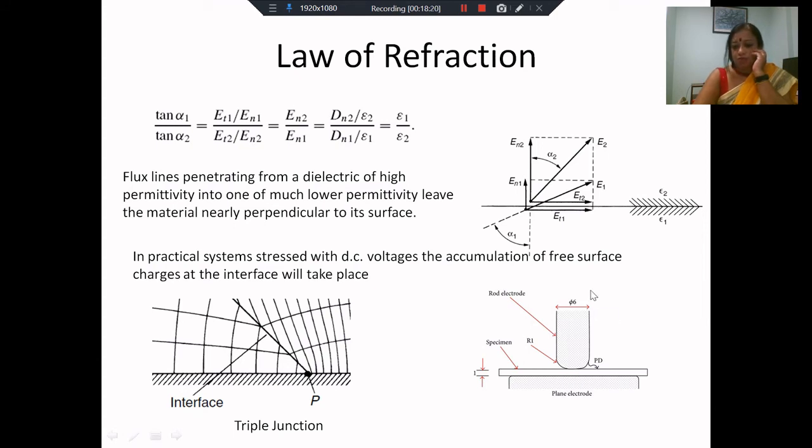This is a rod plane electrode, and there is a chamfering at the edges. Now, in this very small region, there is a very small gap. Here I have magnified the gap, and you can actually see it. In reality, you may not even be able to see it. Suppose you have a rod electrode which is sitting here. It seems that the rod is completely flush with the electrode. But what might happen is at the center, right at the tip, there may be an infinitesimal gap present.